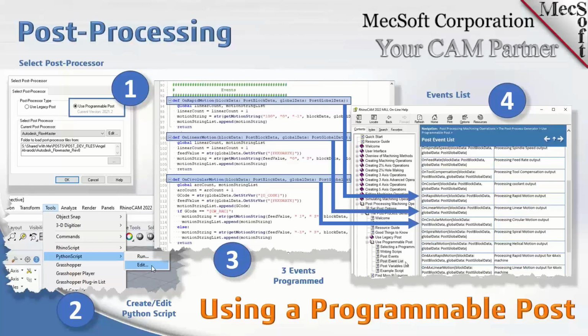And when the system, as it's cycling through the internal toolpath, hits rapid motion, that'll be considered an event. Whenever there's something interesting happening in the toolpath, an event will be triggered. And what Don is showing here on the right side, labeled number 4, is the help file that lists all the events that are handled.